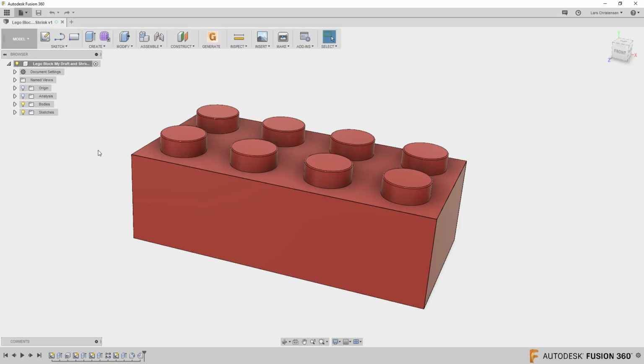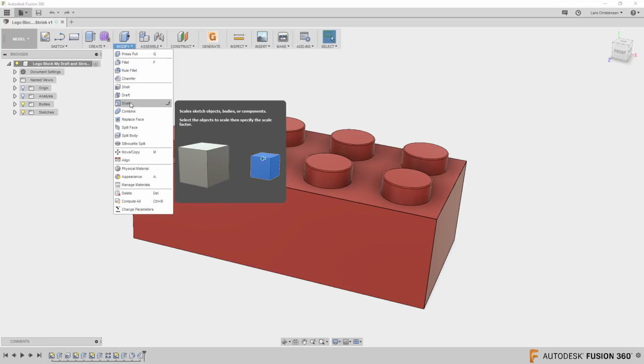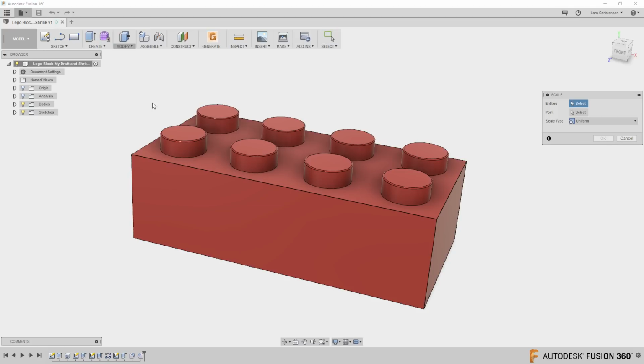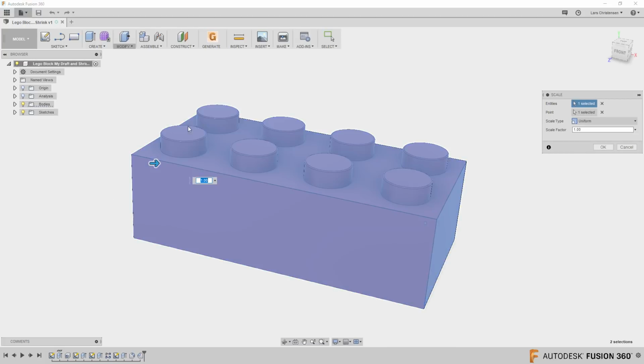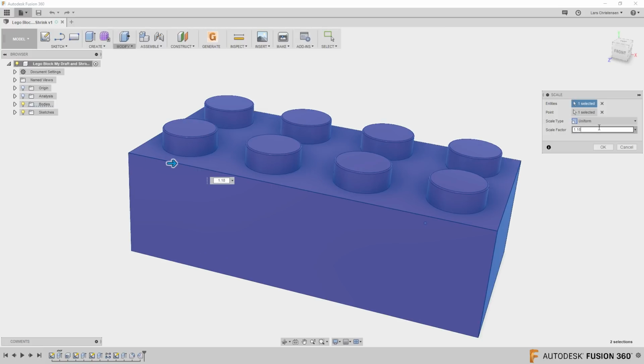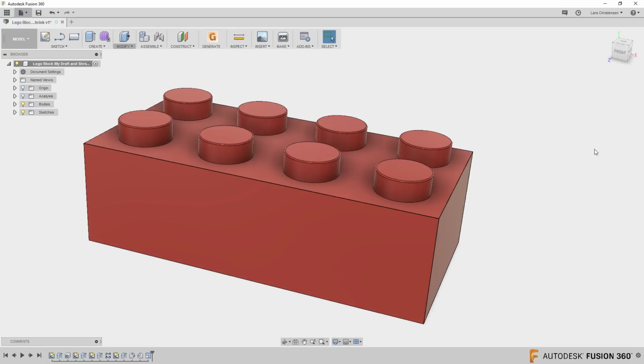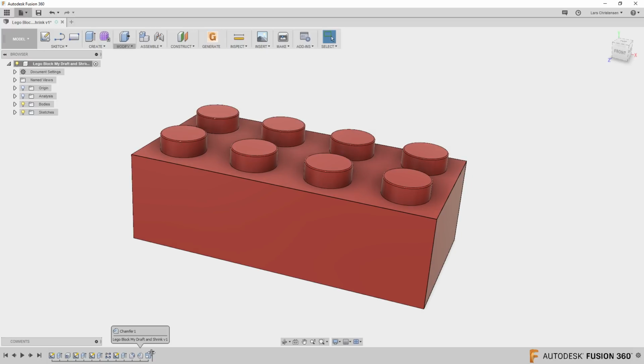Now, with shrink factor, you normally make the mold a little bit bigger because the plastic shrinks as it cools down. The way you do that inside of most CAD systems is as simple as a scaling factor. So you can click Scale, select, in this case, the block, and then add some kind of scaling factor depending on what kind of material you use. I'm just going to hit OK here, and now this part is actually bigger. Look, if I go back, small, bigger.